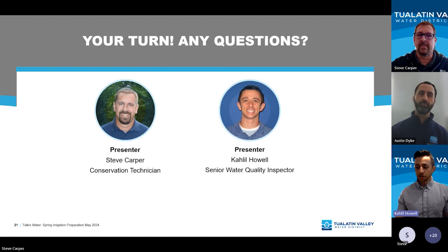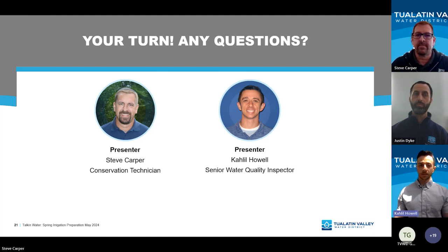There's a little set screw on the retrofittable hose bib vacuum breakers, and its intent is to make it a somewhat permanent installation, so it couldn't just be taken on and off at convenience. So I would suggest tightening that down. Any follow-up questions to that, I'd be happy to answer as well.